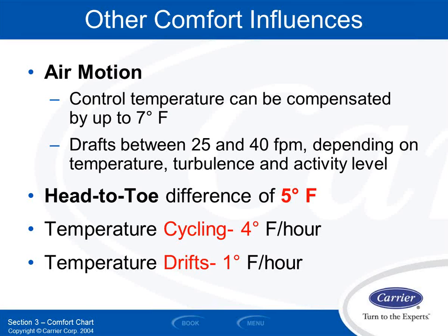And then everybody puts electric space heaters under their desk, and you guys know that whole drill. So it's a really big deal not having more than 15 degrees above the space temperature for overhead heating systems. That's the absolute maximum.